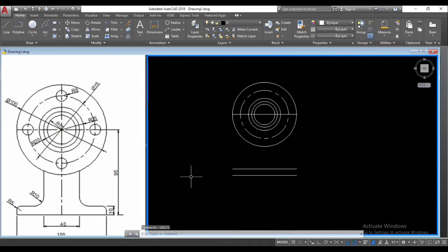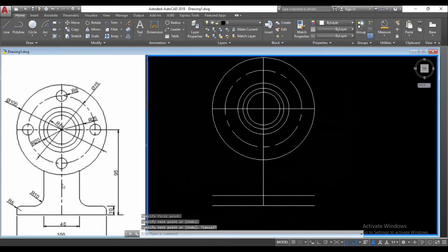We'll just leave those for now. We'll look at that in detail in another video. So I am able now to draw a line, the center line from the quadrant here all the way down to this point. So that's indicating my center point, right? And from this center line here, we have a distance of 40 for these two lines which are parallel to the center line. So we can use offset command again to get those.